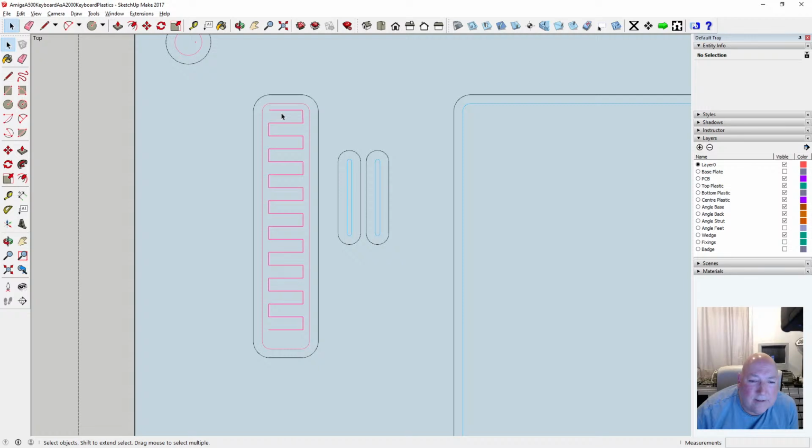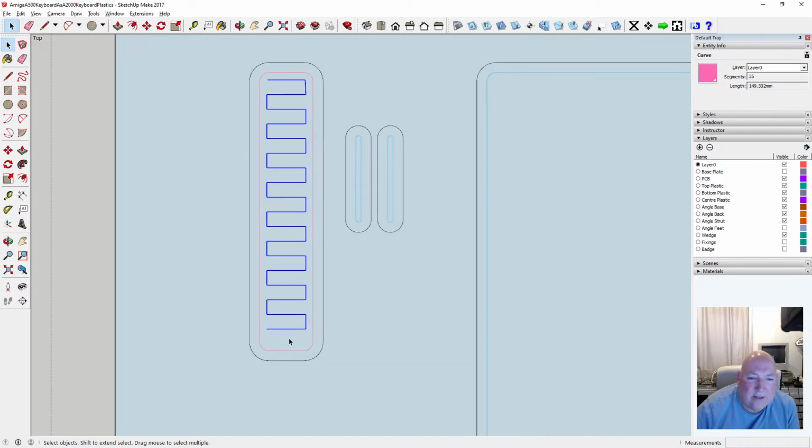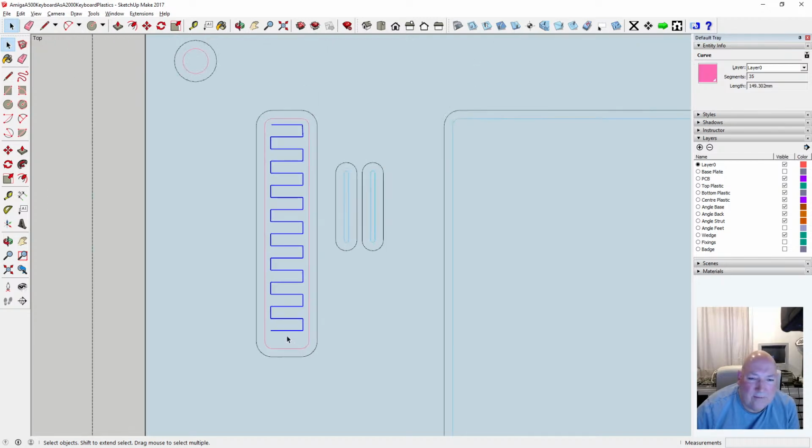Can I copy that? I don't know if you can. I don't know if you can draw this stuff. Can you draw it? No, it wants to. You can copy it. It just misses a bit. The code is normally for big stuff. For doing small stuff, it has a bit of lacking going on. So basically, what'll happen is it'll mill out, but it'll leave a piece of plastic sat there, and you'll have to scrape it out with your knife. You don't want that, really.